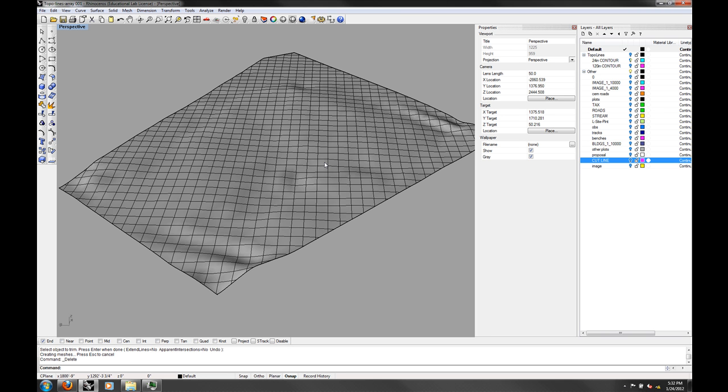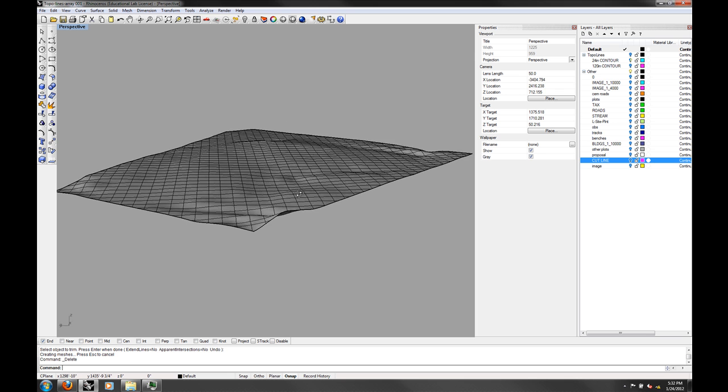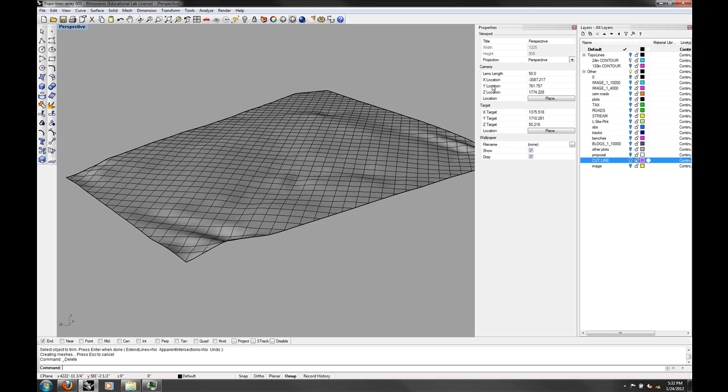You're going to extract the points from the curves. You're going to use that to create a patch, and then you're going to trim out the patch to get a surface model. This isn't a solid. We can talk about how to do that later. It's also not extremely accurate.